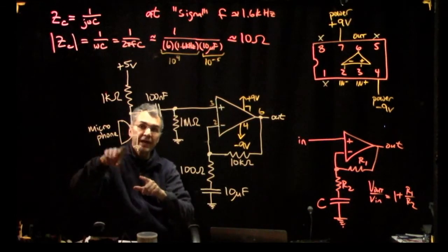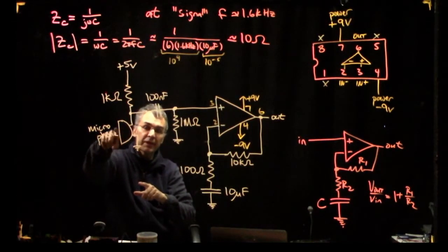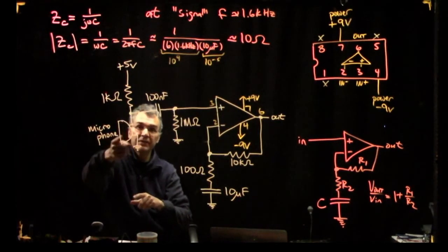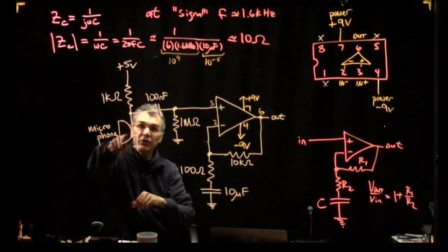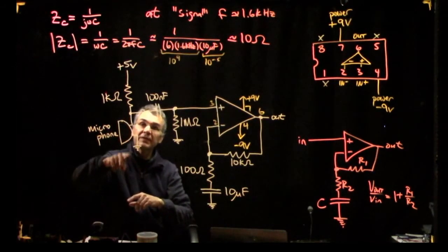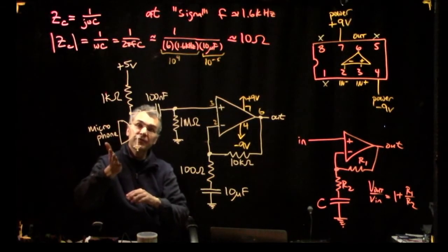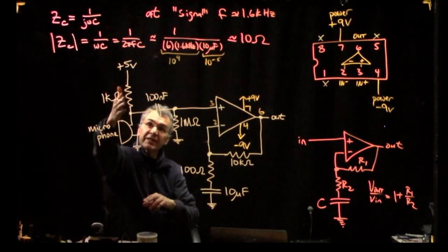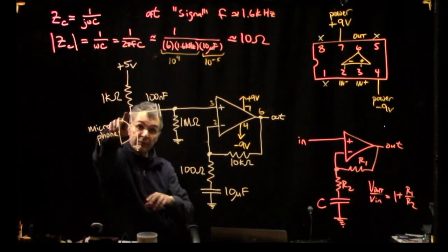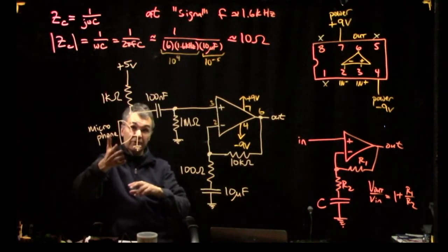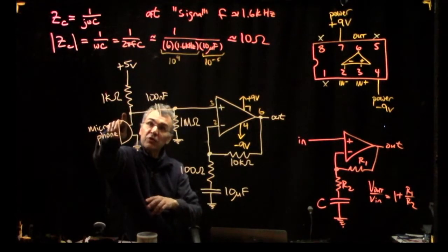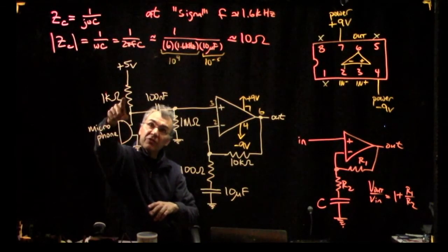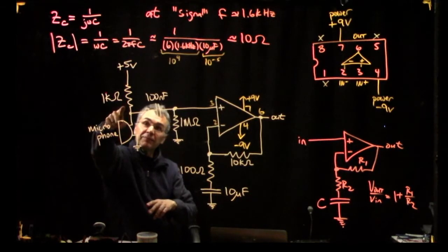Now this microphone, actually, it wants to be powered. There's a little field effect transistor inside it that gives a little bit of amplification. So it wants to be pulled up to like 5 volts. So it wants to sit near 5 volts, but it's not exactly at 5 volts. Because if you connected this directly to 5 volts with no resistor, then this point would just sit exactly at 5 volts and you would get no time varying signal. So we connect it to 5 volts through this resistor, and then the current varies a little bit, which causes this voltage to be a little smaller than 5 volts.